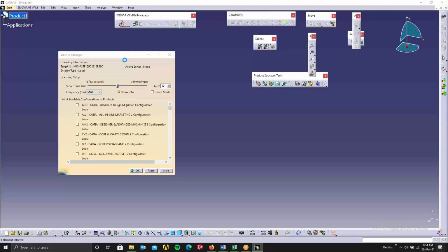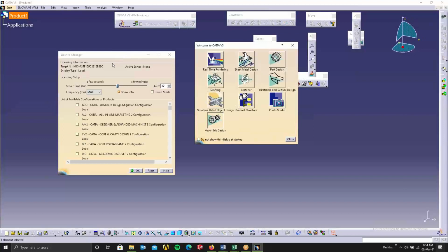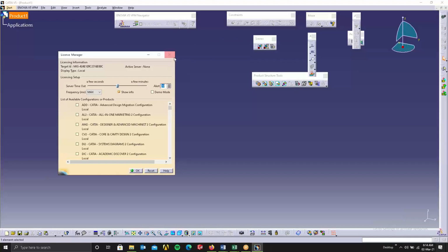But these are the angles that we use. In dimetric, we use two similar angles. In isometric, we use 30 degrees only; it is inclined at 30 degrees on both sides. In dimetric, it can be any other angle apart from 30 degrees, less than 90 degrees. So you should see that.